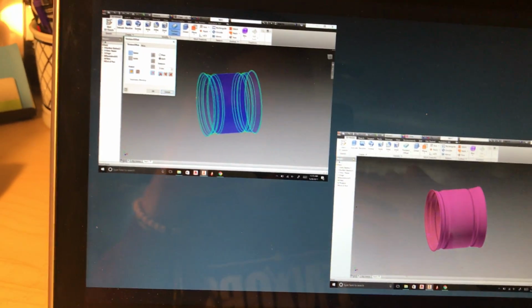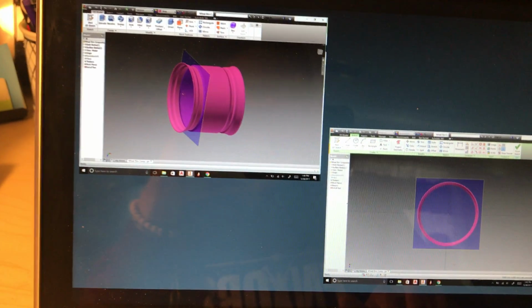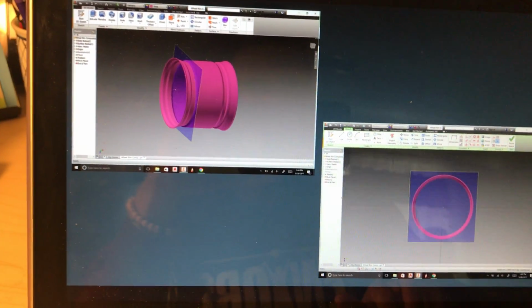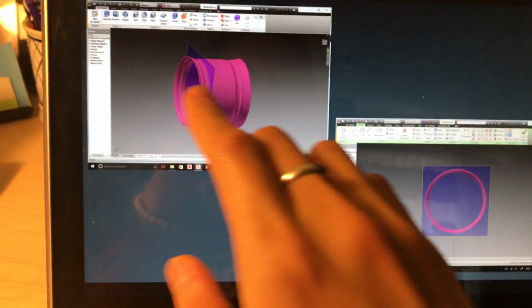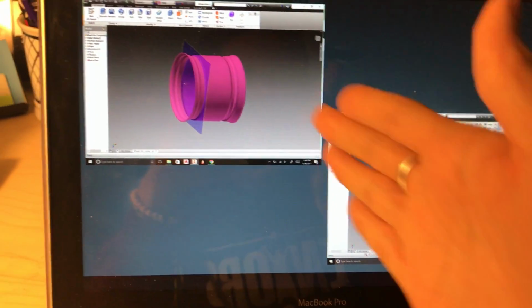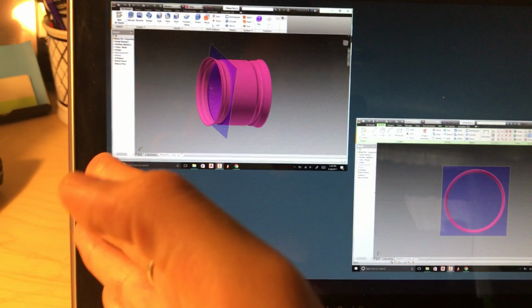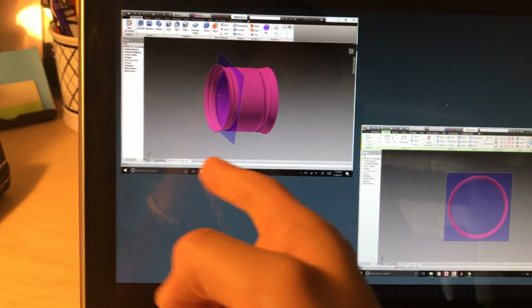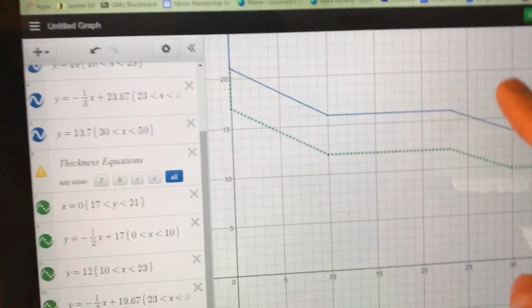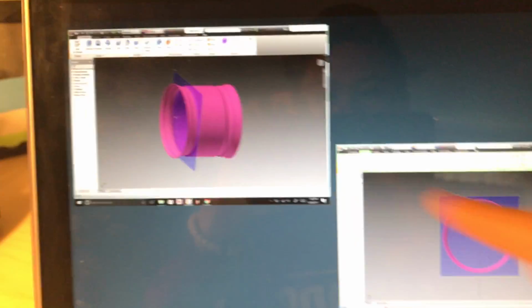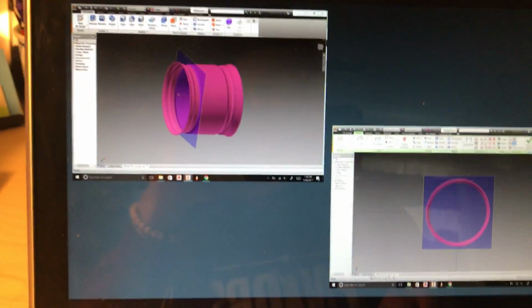This is just me changing the color. And then this is where it gets a little more complicated. In order to make the front portion of the rim, I had to designate a plane. So I just took a YZ plane and moved it to the left a little bit. That's what happened right here. I put it right where this little intersection is, so there's still a little bit of a space for that.